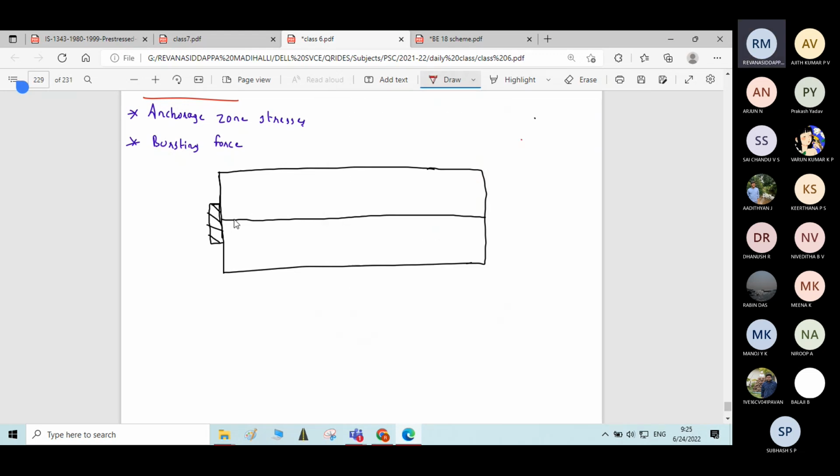Now, when the wire is stretched to the required pre-stressing force P, and is released and anchored at the ends, initially we stretch the wire, and after stretching we anchor the wire by using anchoring devices and an anchoring plate.